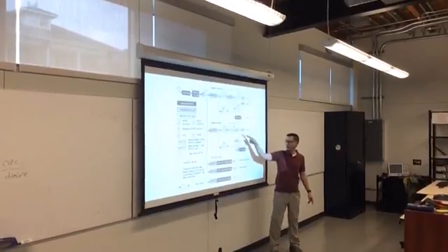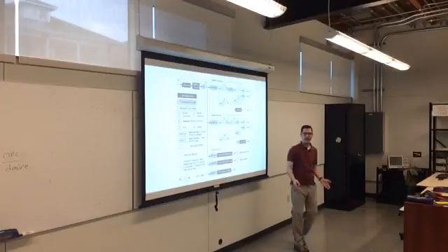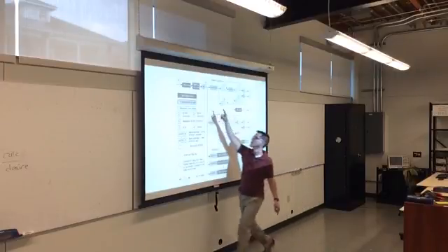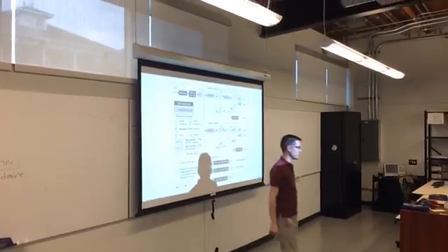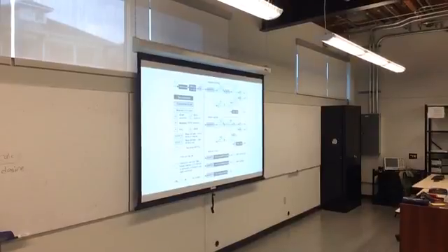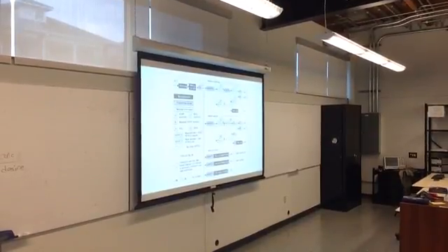So it's a complicated diagram, but you can automatically ignore half of it. And you're going to need to implement every box. There is going to be a piece of code that you write. Like you're going to need to write one line of code that sends a start bit. You're going to need to write one line of code that sends the address plus the read or write bit. You're going to need to write one line of code that waits for that acknowledge or not acknowledge. You're going to need to write one line of code that transmits your data. So your lab is not a tremendous amount of code.